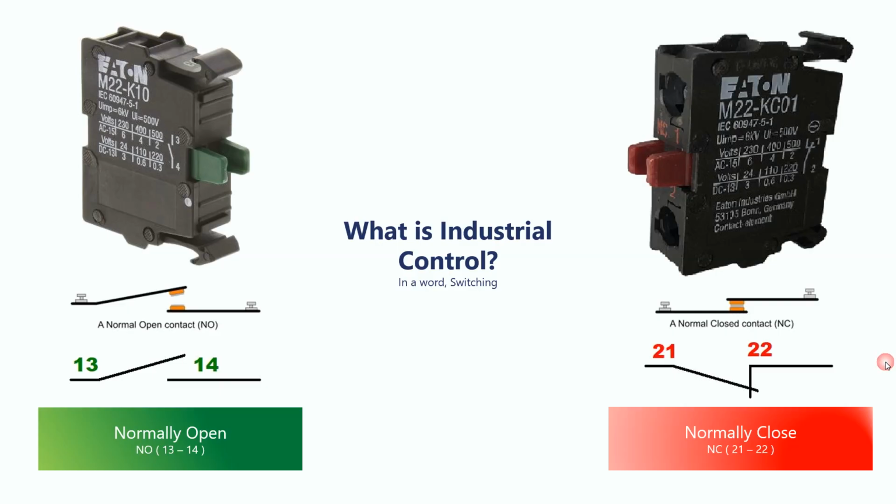So back to the board. Now this is a normally open switch. It is shown by the color green and the numbers 13 and 14. Any number that ends with 3 and 4 usually depicts a normally open switch. These are industrial standards. A normally closed switch is indicated by the red color, and it is often shown by numbers ending with 1 and 2, for example 21 and 22. So something to keep in mind.